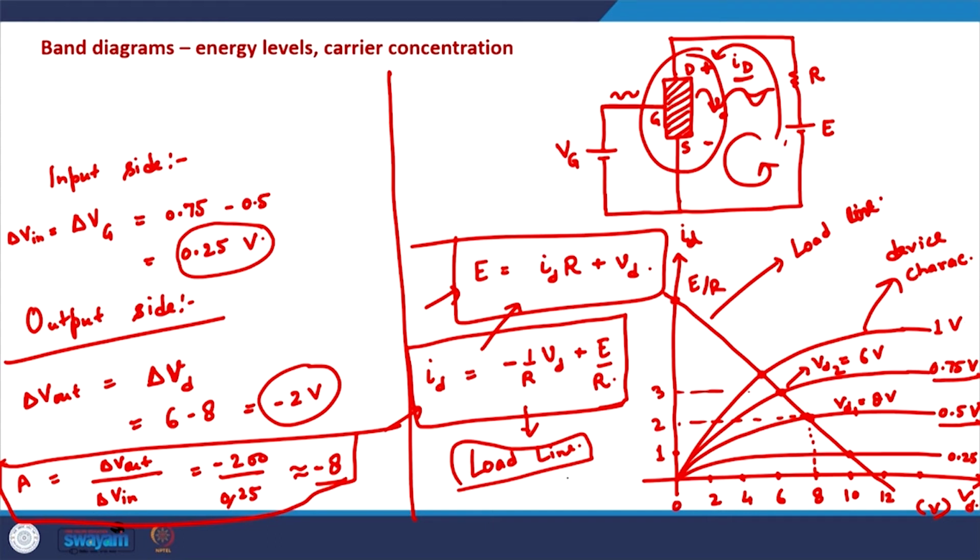So in this amplification, no energy is getting produced out of zero. So it is not as if we are able to produce a large signal out of a small signal, because we need to maintain the proper DC biasing conditions. So there is a net loss of energy, but a small AC signal can be converted into a large AC signal, and that is how the amplification can be achieved in the MOSFETs.